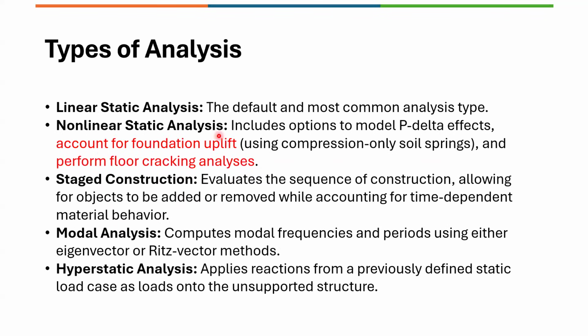So the types of analysis typically used are linear static analysis, and the other one is nonlinear static. Nonlinear static is used, for example, for foundation uplift. For floor slabs, you'll be checking cracked deflections, short-term and long-term deflections. Other types of analysis also possible within the program are listed below.